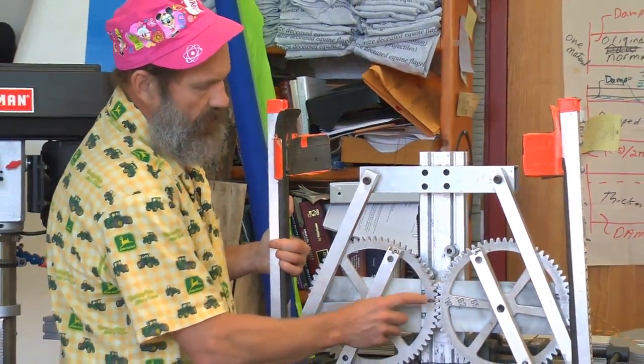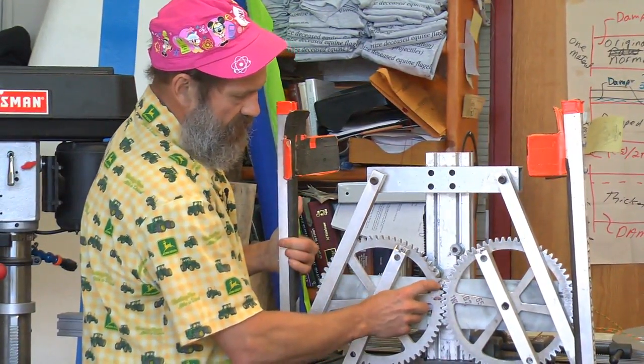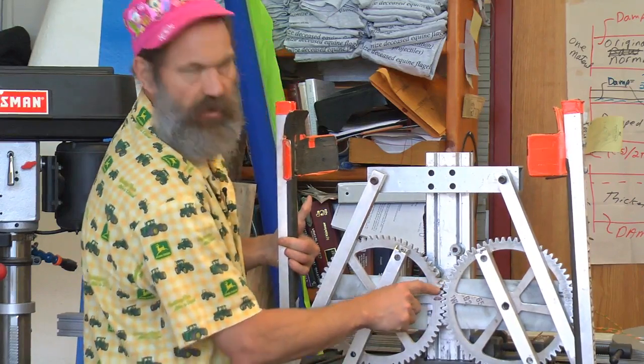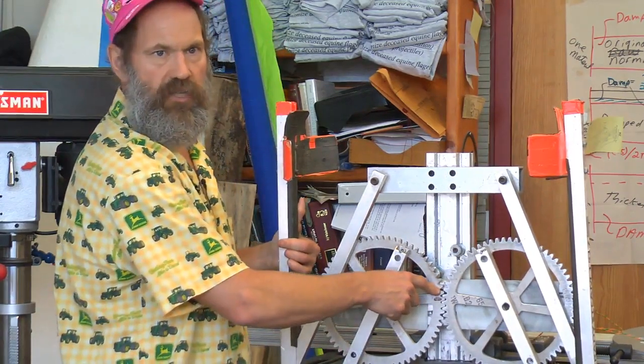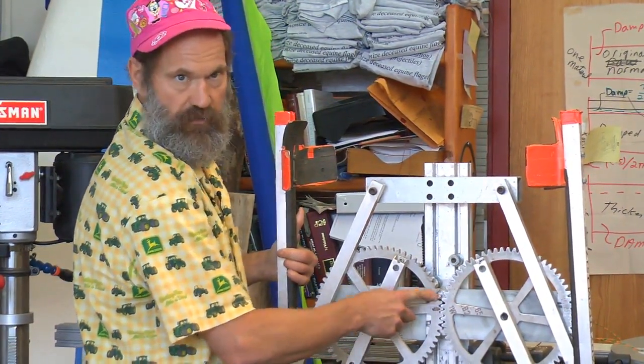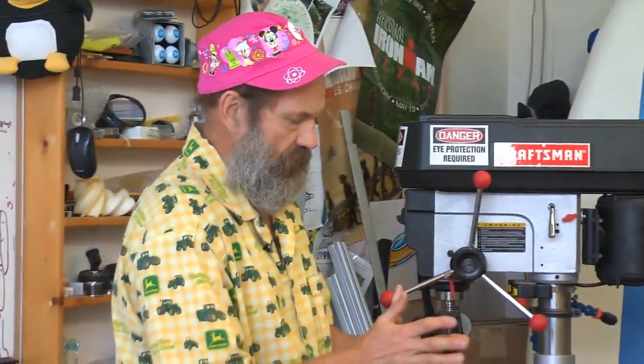displacement modes. Well, it turns out using energy methods, you can calculate the deflection due to the bending and the shear as a function of the varying cross-section of the tooth. Very straightforward to do. And now you have your closed-form solution for the stiffness of that gear tooth, and that would allow you to get the stiffness of your rotational mechanism governed by those gears. It's stiff enough.